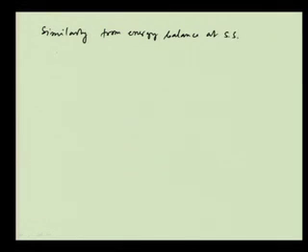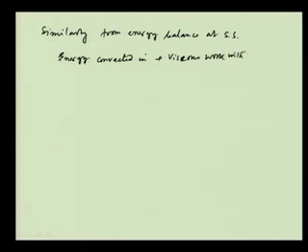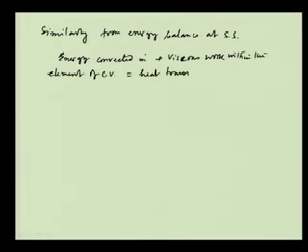The basic equation is like this: energy convected in plus viscous work within the element of control volume is equal to heat transfer in at the wall, which is also an input, and that is equal, at steady state, to energy convected out.